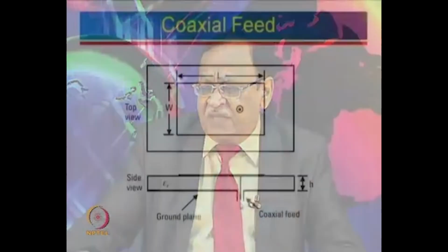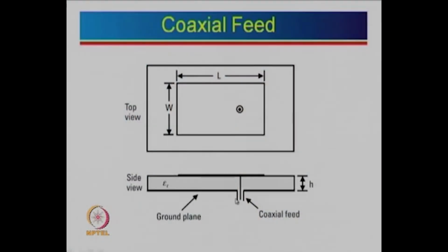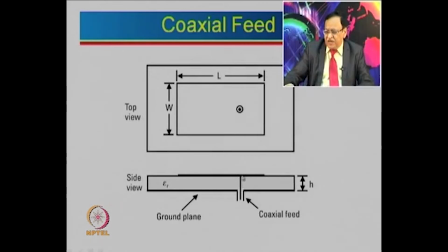Normally, the ground or outer shield of that coaxial wire or connector is soldered to the bottom ground substrate, and then a hole is drilled here, the center pin goes through there, and we solder it to the top patch over here. And that's all a microstrip antenna is. A simple PCB, use a coaxial feed, it needs to be optimized, job is done. So that's one type of feed.